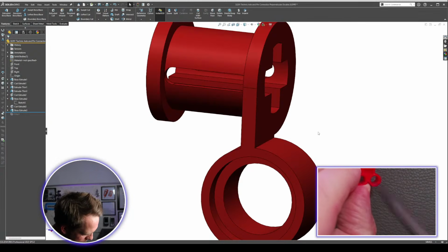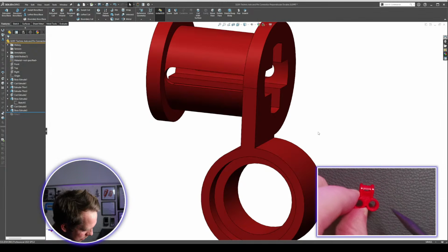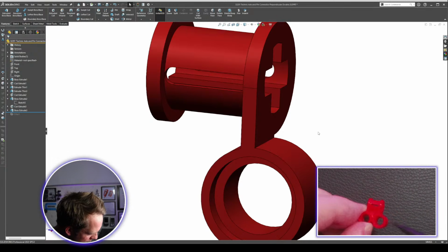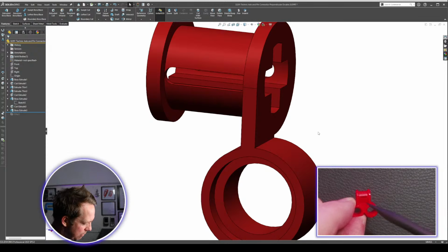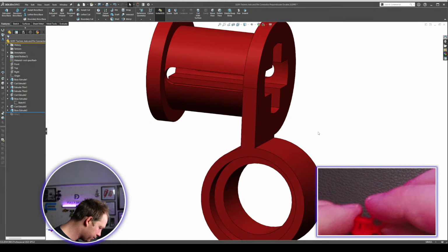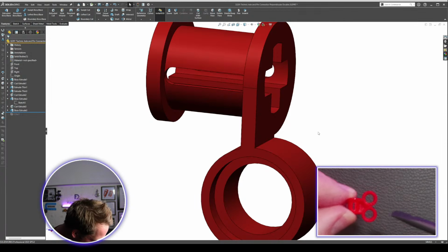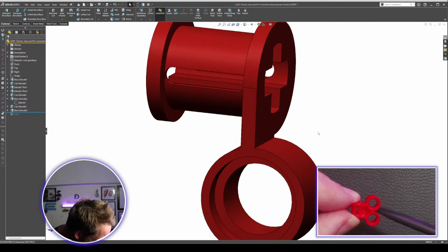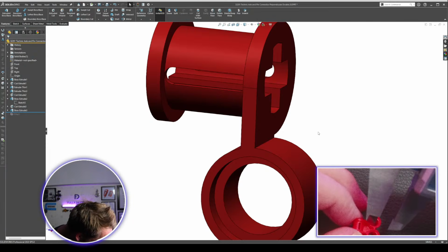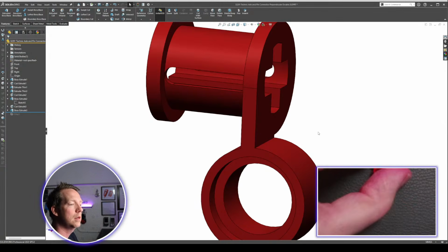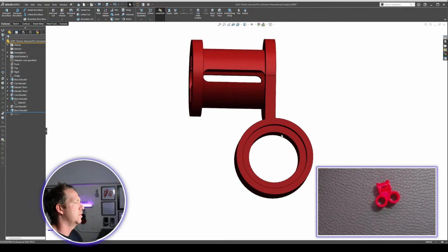And all we've got left to do is this section here, where we've got material. Now, I can't measure how thick that is, but I'm going to assume it's about 1 mil, same as everything else. So if I do half of that, we're going to do 0.5 millimeters. We can also see there's going to be a little gap between those two cylinders. That's filled in with another thick part there, which comes up to that top face. 1.3 mils. So we'll join that in as well.